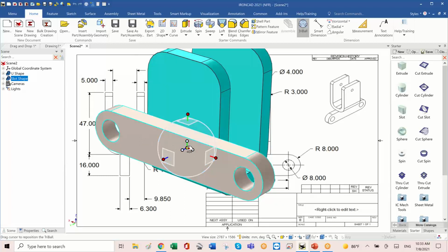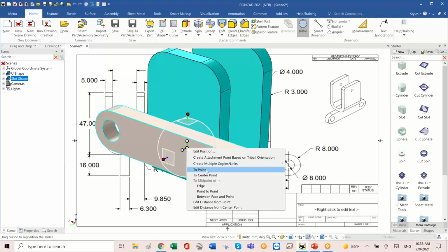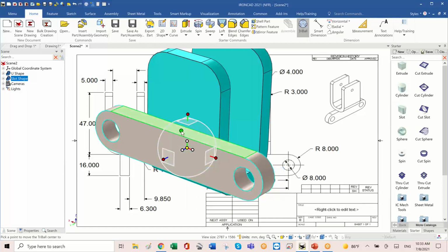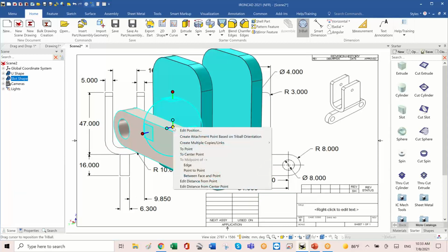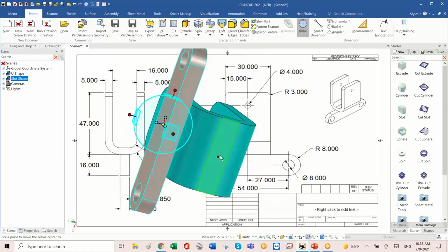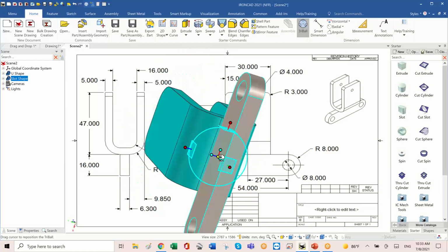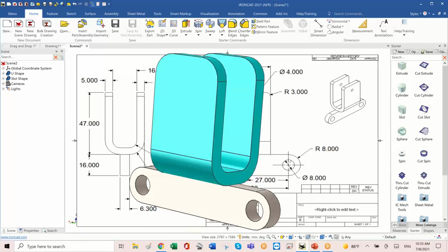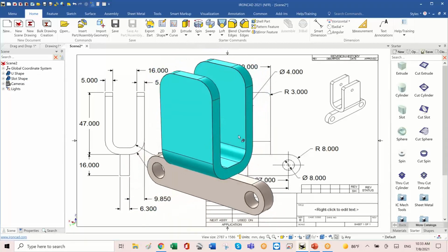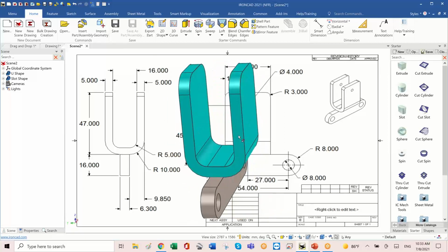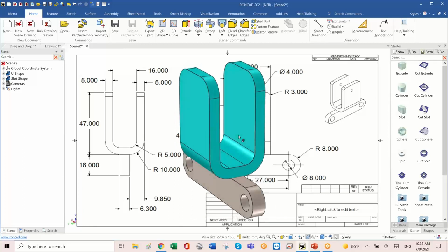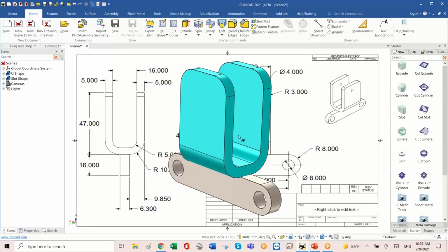And as I said, I want this point, I want to change it, and I want to go where? Right there. Now lock it by hitting the space bar again. Now it's locked. Now I'm going to move everything. I want to move this part from here to a point located on this part right there. And so now, without having to look up commands, I've got this part located exactly where I want it. And that's kind of neat. That lets me do one more quick thing. So that's located in space.